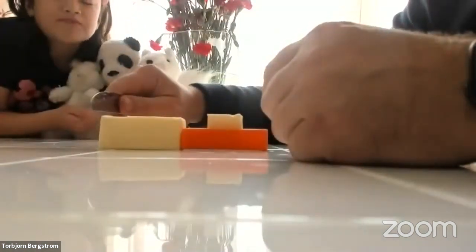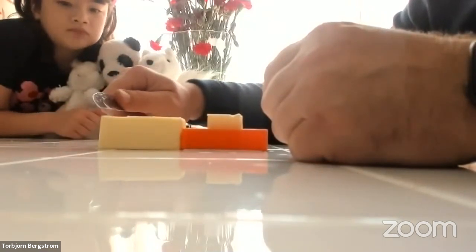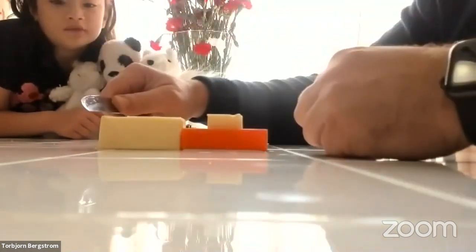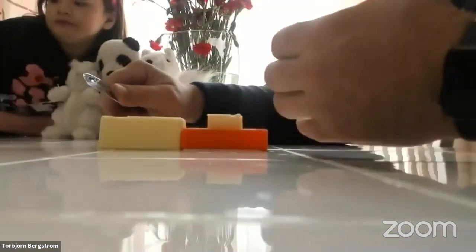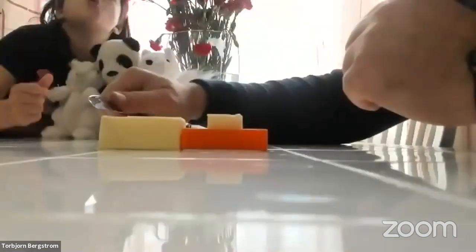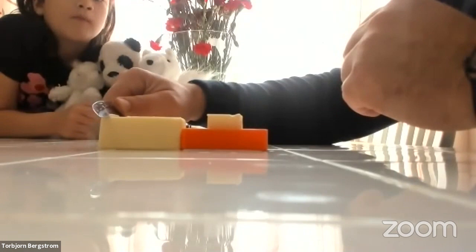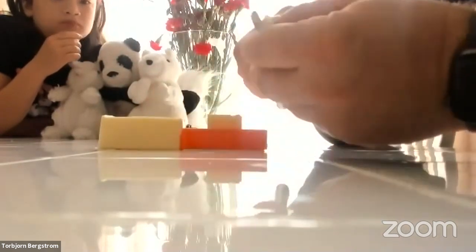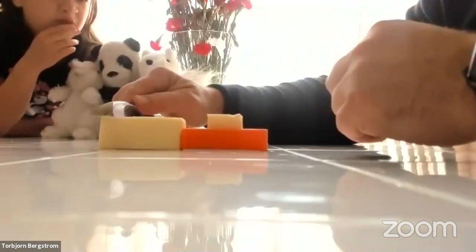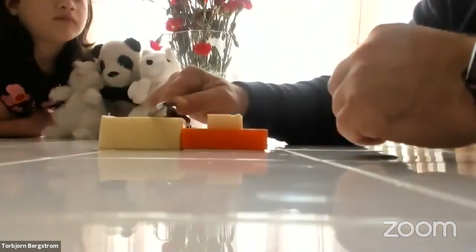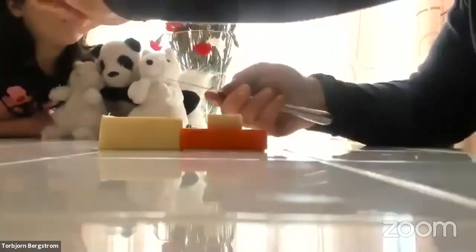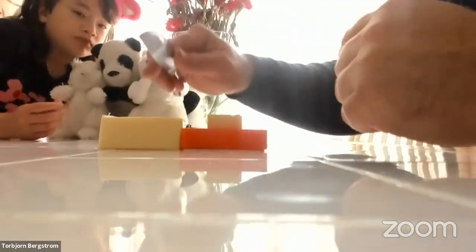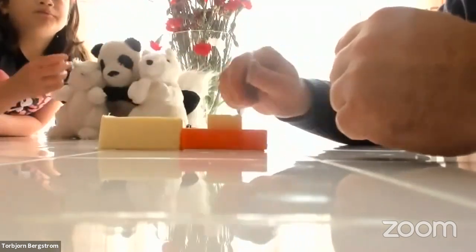But we could, and so if we change the angle of the knife here, we're changing the rake angle as we come across here. So I've got a rake angle of 0 right now. If I wanted to have a slightly positive rake angle, I can put the knife like this. And I'm using the back of the butter knife because the edge is flat. And you could use a steak knife, and then you change. So if you use the steak knife, you'd change the W factor, right? And so I've got a positive rake angle here. I've got my chip forming and sliding on the rake face of the tool. So we can do that with a negative rake angle. And if you alternate between that positive rake angle and negative rake angle, you'll notice that it takes different amounts of cutting force, both to hold the tool down, so that's our thrust force, and the cutting force, the force of pulling it this way.